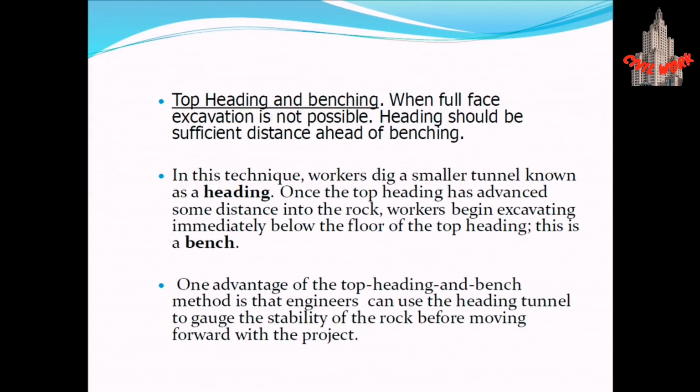Now the second method of tunneling is generally applicable where there is not firm ground. This method's name is top heading and benching. When full face excavation is not possible, where it is not stable ground or stable soil, or when we have faults and folds in the rocky strata, then we will not focus on the previous full face method. We will now focus on the top heading and benching method.